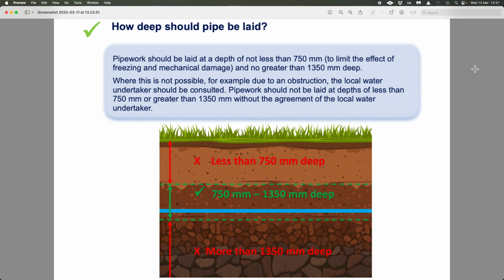And we know that we have a couple of parameters. The water regulations state that outlets should be approximately 38 degrees centigrade. I tend to go a little bit higher than that and blend down afterwards with mixing. But that's just because I'm looking at 10 degree water coming into the system and a 35 degree delta T, which will give me a flow temperature coming out of my taps at 45 degrees.